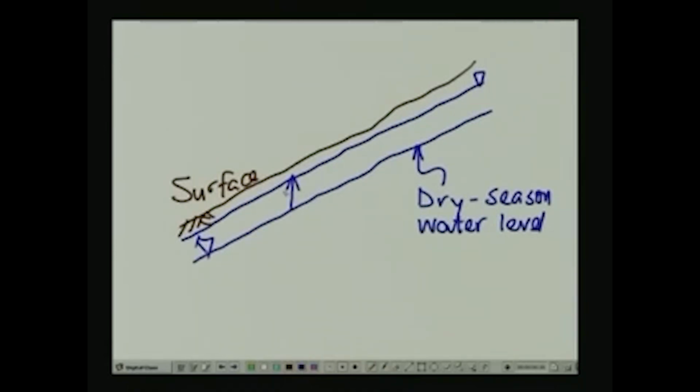and because of the decreased effective stress, the frictional strength of the soil is also going to decrease. If the decrease in soil strength is quite large, then this process of raising a water table is going to cause the slope to get destabilized. So this is how a slope could get destabilized during rainy season or wet season.